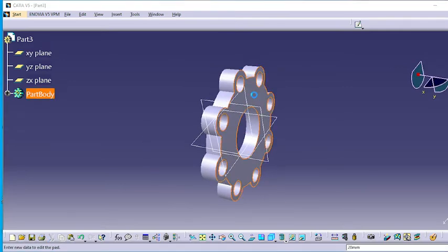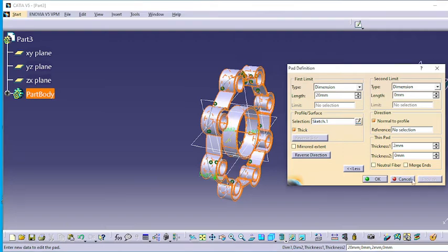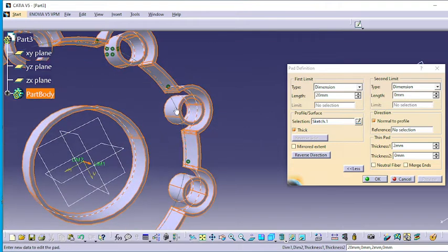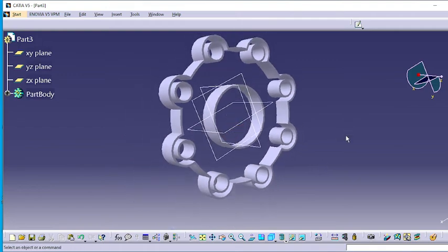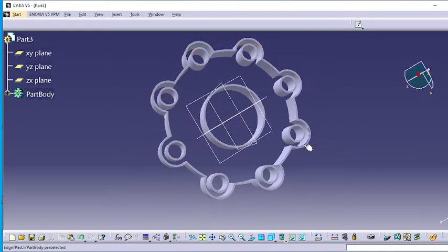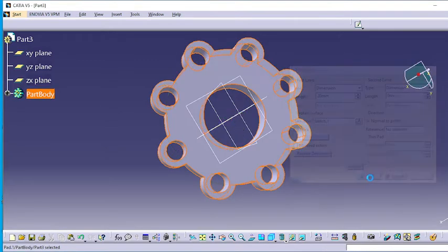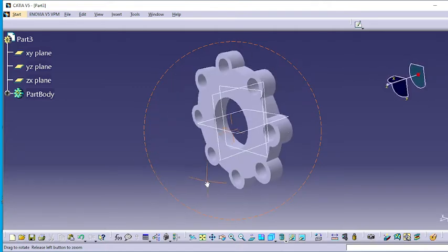In the middle I want to require hollow. So for example, you can go to more options, thickness options. How much thickness are you taking? Now you are seeing this, so all of them add thickness to that sketch. For example, here there is a circle, this circle takes 2 thickness, this curve takes 2 mm thickness. 2 mm material only we are creating, and the remaining will be hollow. Okay, but if I don't require this, the total body will be solid. You switch off that thick option. Okay, that is the use of the thickness option.